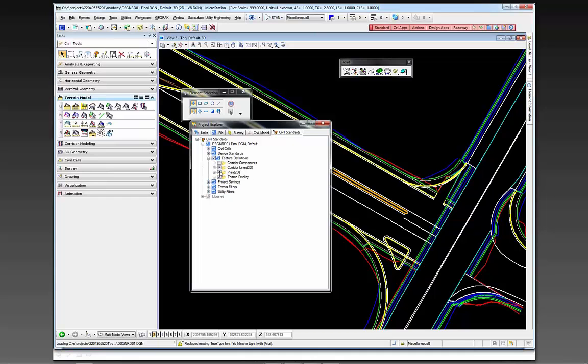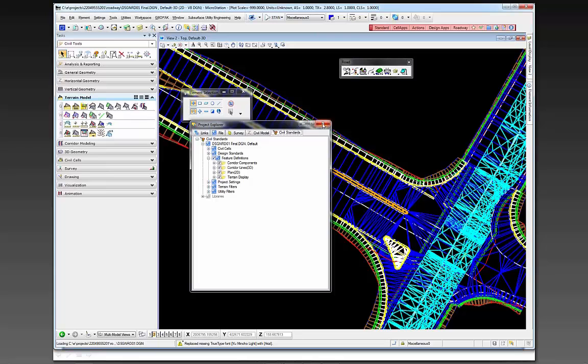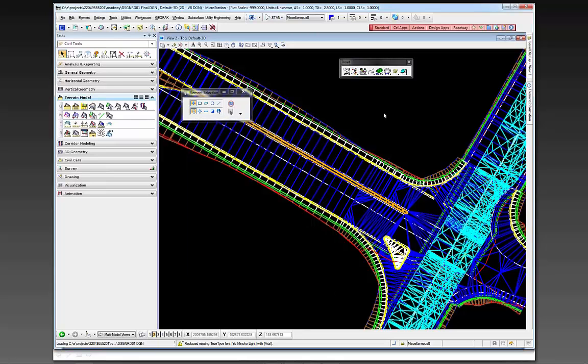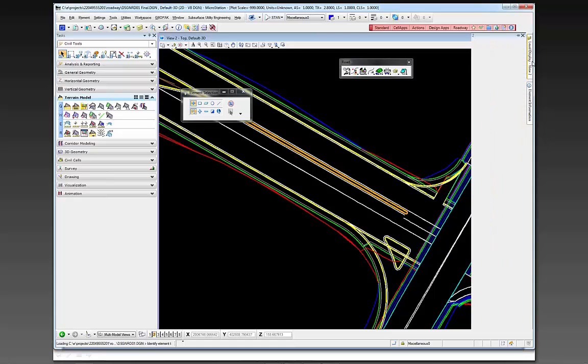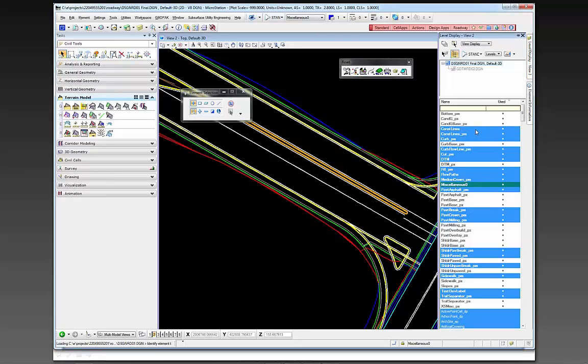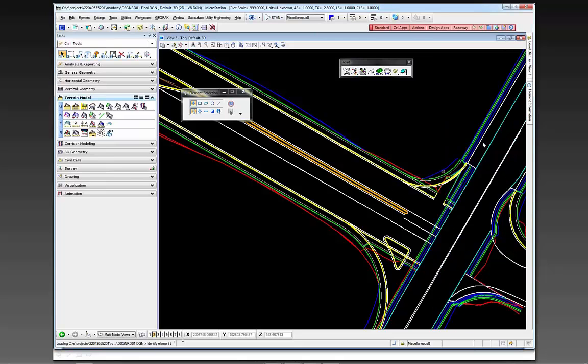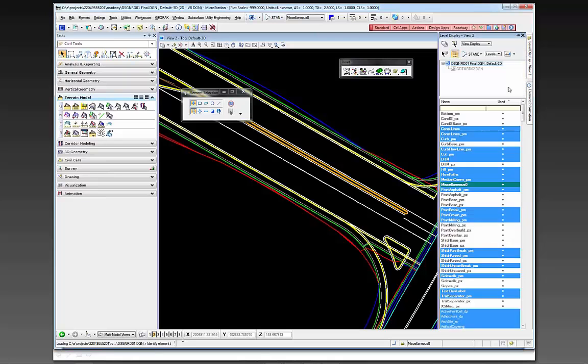So that's one way to control how things are displayed. Another way is to use a couple of function keys that we created. We created an F9 function key, and what F9 really does, it goes in and it turns off everything that has a PX, which is basically where the components are, and any level that is PM is what's being displayed in the 3D model, okay? So that's a proposed model of the curved flow lines.